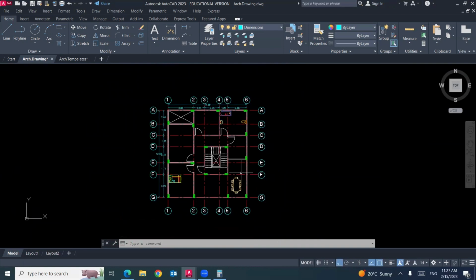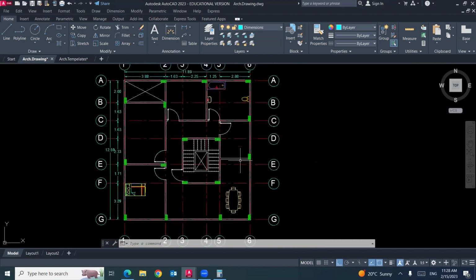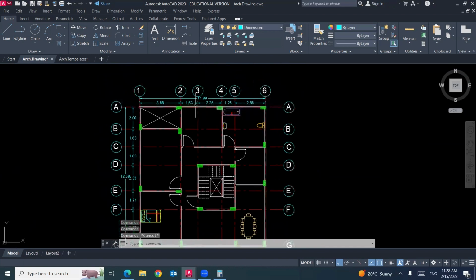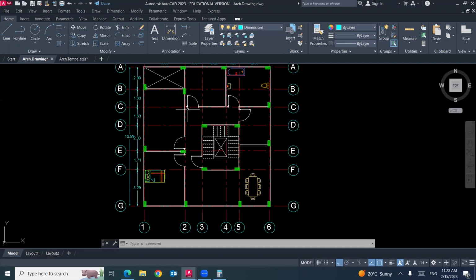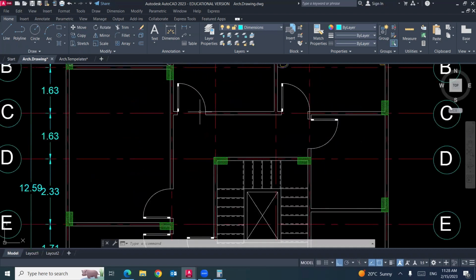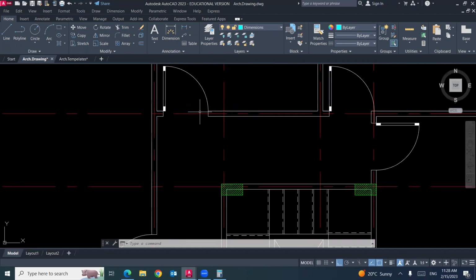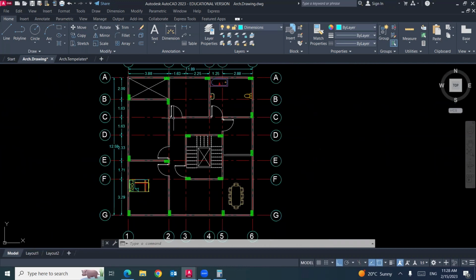It's very easy, very interesting. Keep these steps in your mind. These walls are drawn using a multi-line. I will start first with the center line. Label your circle with text, put your dimension, draw your walls, regardless of whether you have doors or not. And then you will put your door, and then using trim, you can delete the part of the wall bounded by the boundaries of the door.